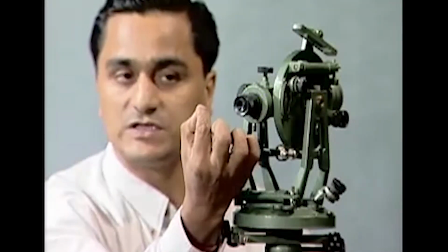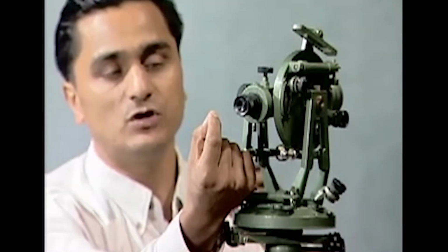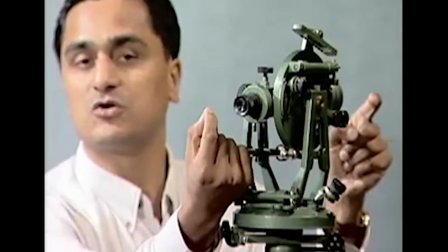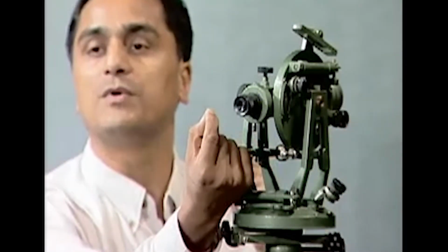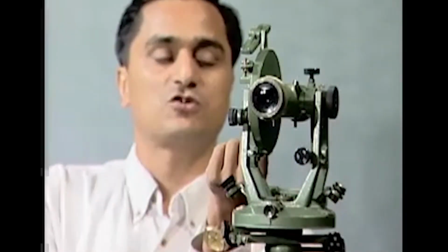But now what has happened to the line of sight? This point has shifted sideways. So now the center of the cross wire is here where I am holding it. If the center of the cross wire is here and you are looking through this line, the center of the cross wire and the center of the objective, what will happen? Well, in this case, let us say that's the point where the center of the cross wire is, somewhere here. Ideally it should have been here. Now start thinking, you have to visualize it.